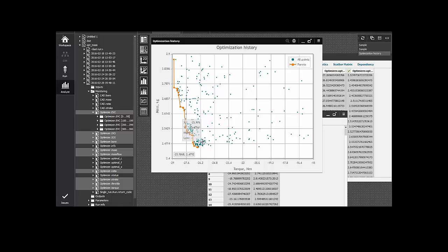Just know that it's a two-objective optimization problem. So we have not a single solution, but a whole set of solutions. Pareto optimal means that you cannot improve one and keep the other. So all the points are inside this line. The torque has the minus sign, so the better is here, to the left, and the lower mass is of course to the bottom.